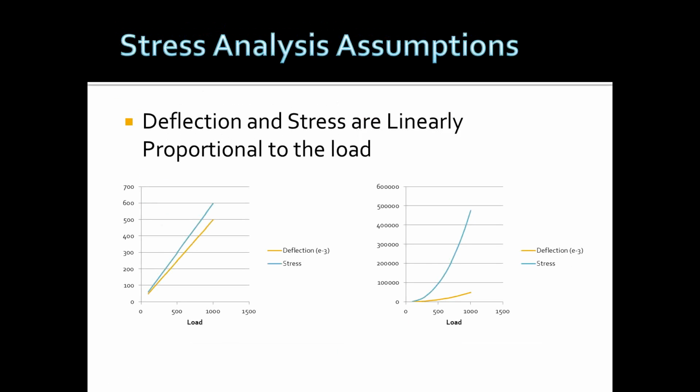So because there's not a straight line, you're dealing with a non-linear analysis. On any kind of material that's non-linear, again, plastics, rubberized materials, polymer materials, and again, wood, we have some cabinet makers and furniture shops, and they want to look at building chairs or tables or shelves or anything to hold certain weights. They can to a point, because wood does have linear progression to a very small point, and then beyond that it becomes nonlinear.